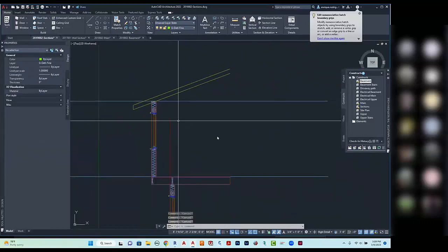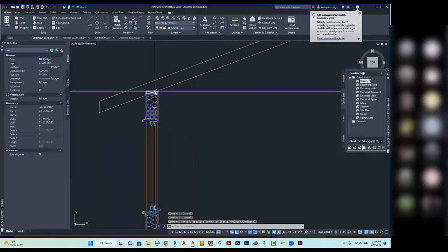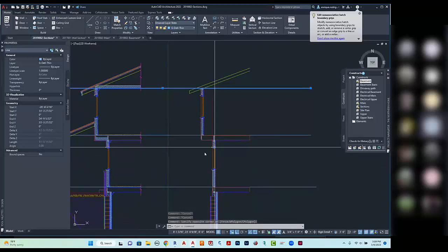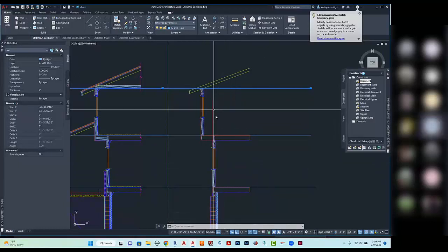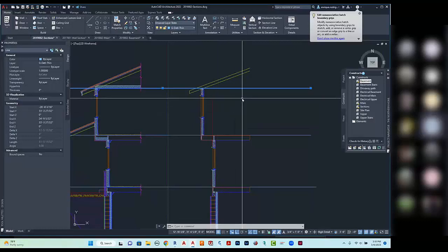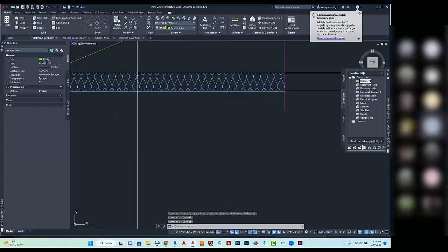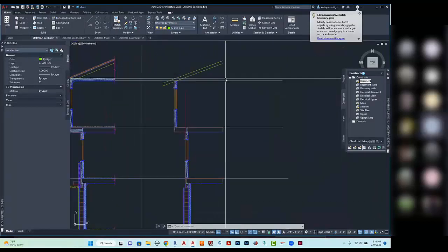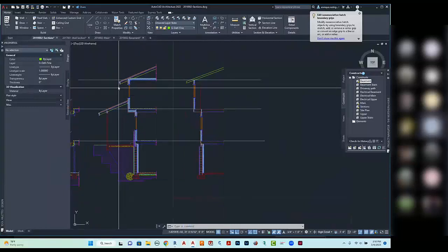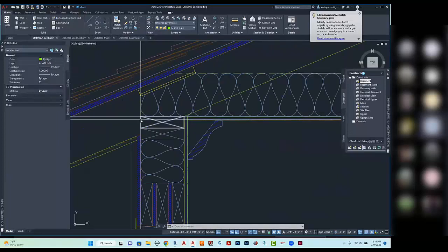All right. This represented the height of our wall, which is 8'2". It matched the one that we had down here at 8'2". And we also have what we call ceiling joists in here. Now our ceiling joists can be 2x6s or 2x8s, depending on the spans that we use. We're going to go ahead and draw them at 2x6. We're going to use a 5.5 inch insulation here.